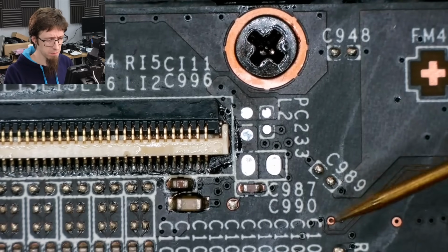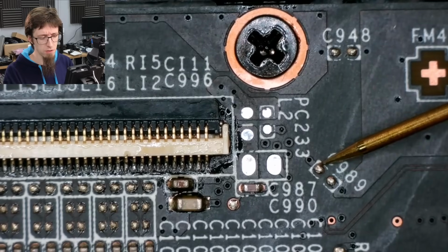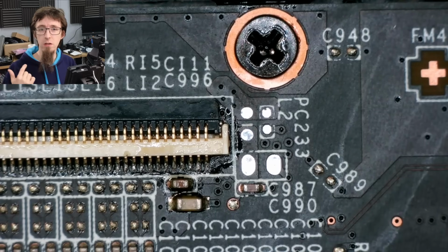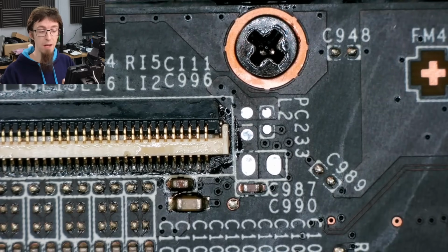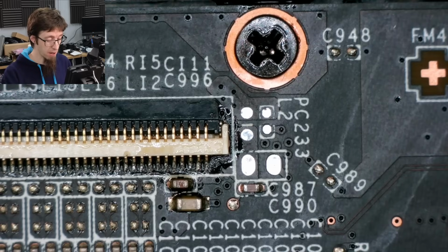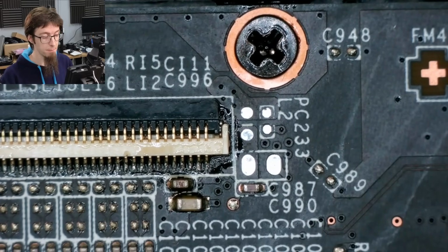And you can tell that something is a no stuff because you get these perfect bumps of solder where there is a solder blob there, but nothing has ever been in it. If a component has been knocked off the board, then the pad will be flat, or it'll have a divot in it, or it'll have a crater or something where you can see that a component was seated there. But a perfect little bump like these guys, that's no stuff, so we don't need to worry about that.